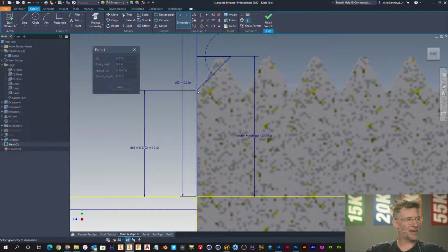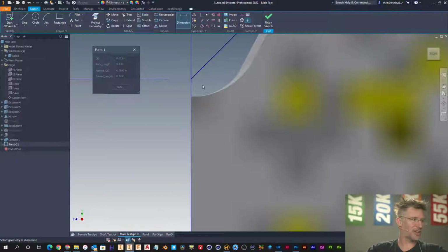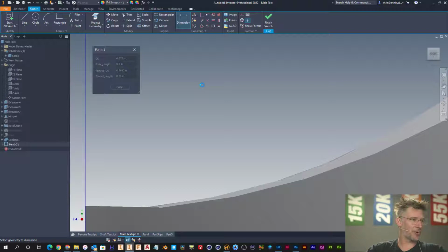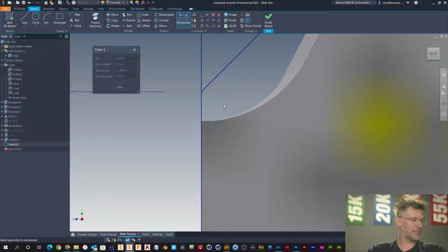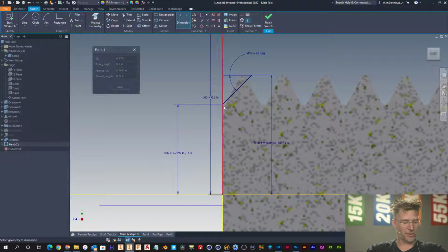This is why I don't like doing it this way, because the Cool Orange is not technically cutting correct threads. They're cutting threads for you to physically see, but they're not geometrically correct. They might argue with me on that. But the reason I know that right now is because, look, if I cut my chamfer right here, I'm completely off the part, and we want a smooth chamfer cut. We don't want any bit of that chamfer being off the part. If I run this chamfer around, you'll see what I'm talking about in a second.